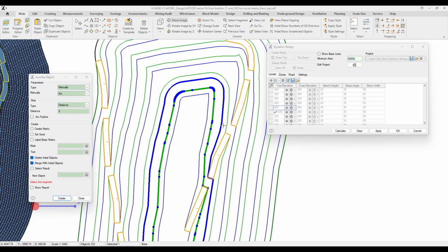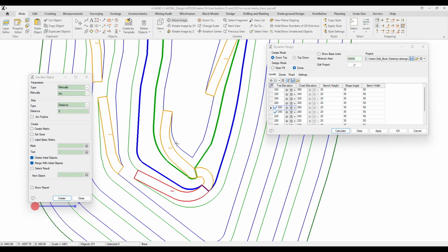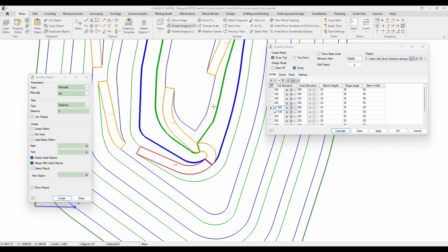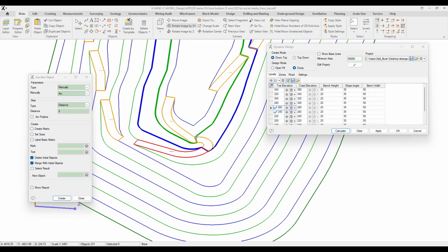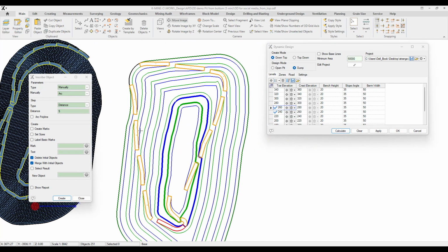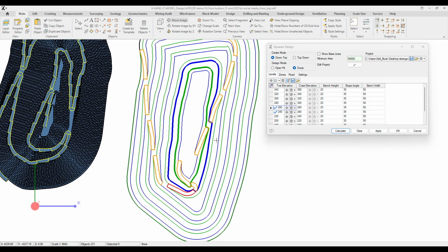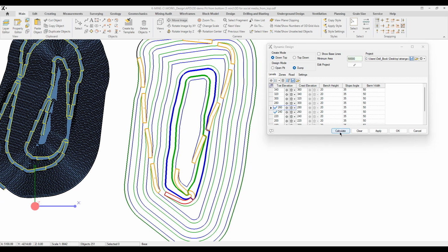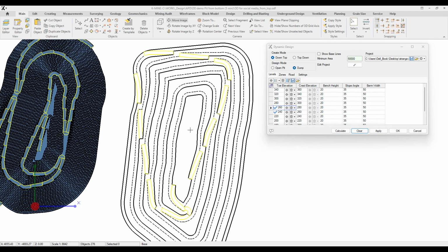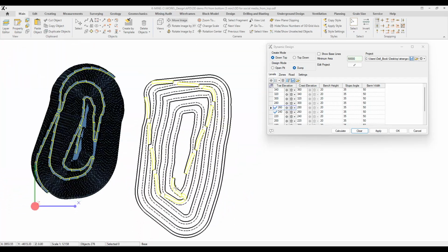Since there's obviously not enough space for the last ramp on one of the roads, we'll add a switchback. The key here is to add a wide enough area to maintain dump parameters and allow lift traffic. The radius parameter is responsible for this. Note that this is the radius and the area is the diameter. Finally, we'll smooth the sharp angles on the last lift to adapt it.